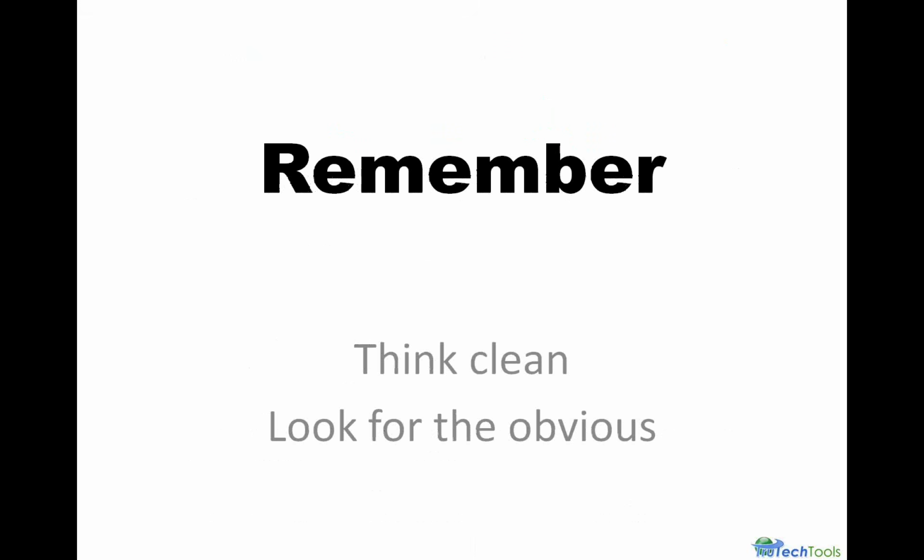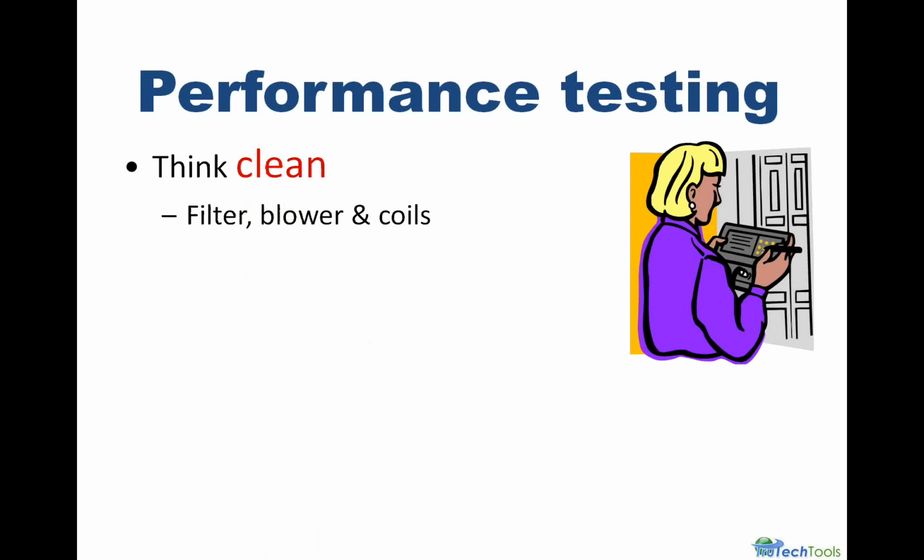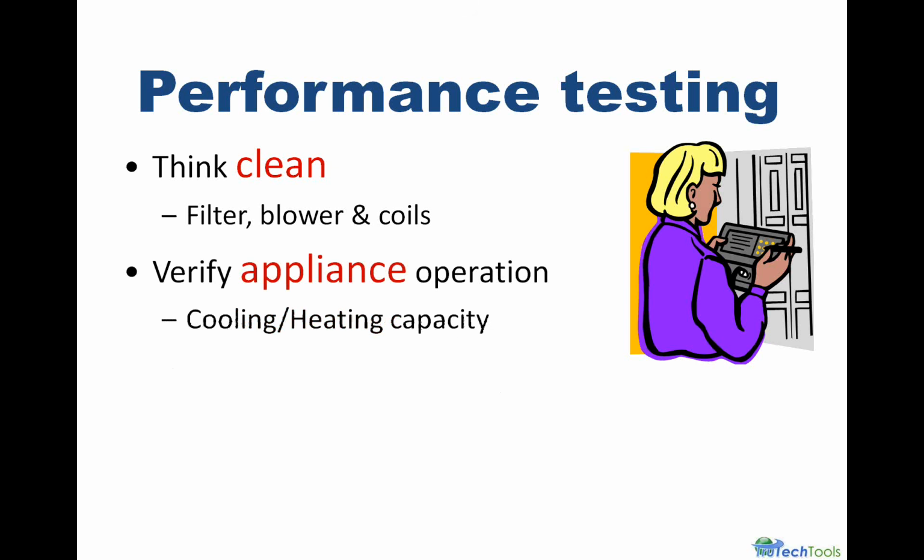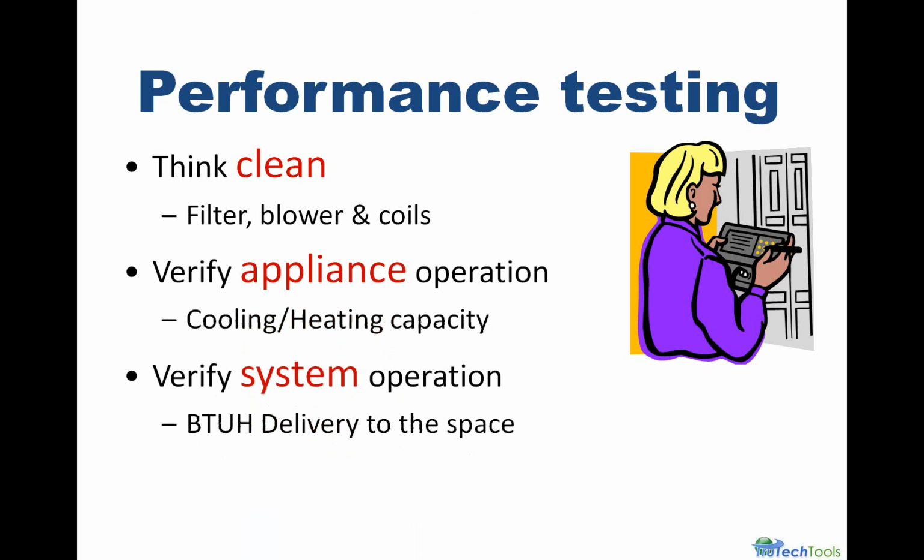All right, so before we get into performance testing, you've got to look at the obvious. Unless we're doing a test-in, and some guys will do a test-in, they want to see how it's performing as is before they do any work. But if we're going to test equipment, new or existing, the only way you're going to get maximum performance out of it is if it's clean. After we get it clean, we're going to verify the appliance operation, and then we can also verify the system operation, in other words, BTU delivery to the space.